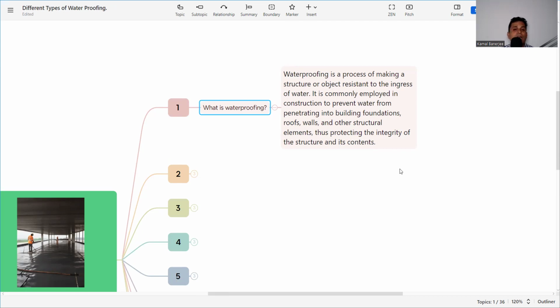So what is corrosion and how do we prevent it? I made a detailed video. Check there, or in the description, you will get full information about the corrosion of steel and how to protect against it. Whenever water is penetrating through this weak spot, chemical ions like chloride, sulfate, and other harmful ions will also penetrate, and eventually break the structural integrity. It will corrode the concrete itself. It will rust the reinforcement itself. So eventually, the structural integrity will be in trouble.